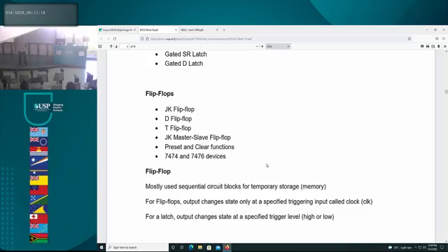What is the 74LS138? Anyone remember that? 74LS138, 3-to-8 decoder, right? 74LS156 is your multiplexer, I believe. Similarly, your D flip-flop comes in a ready-made chip.